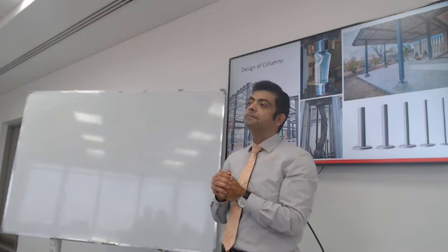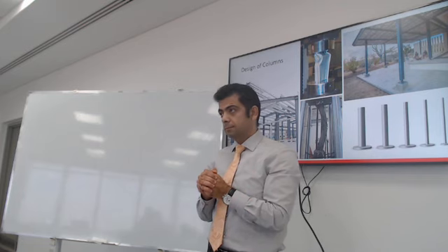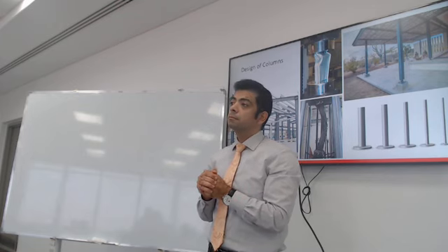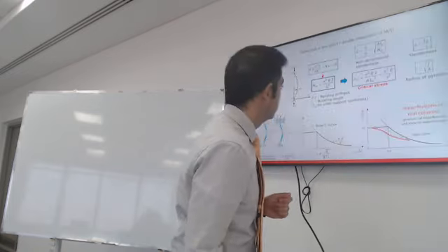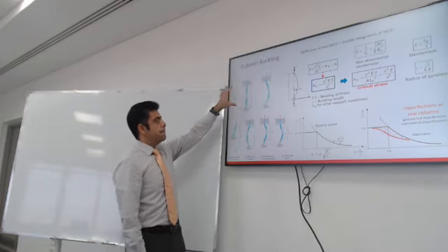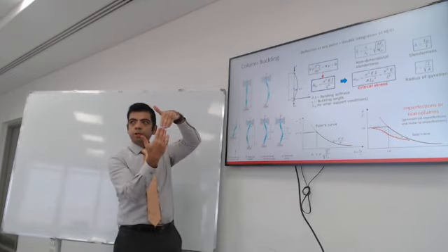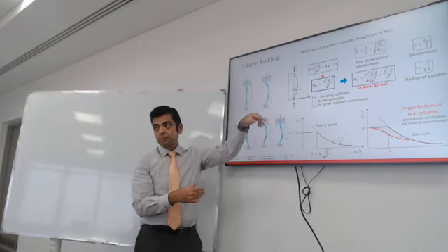Yes. So if it's really long and still within the resistance of the column, and the resistance is still bigger than the load applied, why should it buckle? That's a good question. Let me show you why. Here is what I mean by buckling. If you have a member in compression, you could reach yield and crush that element, or it could buckle.